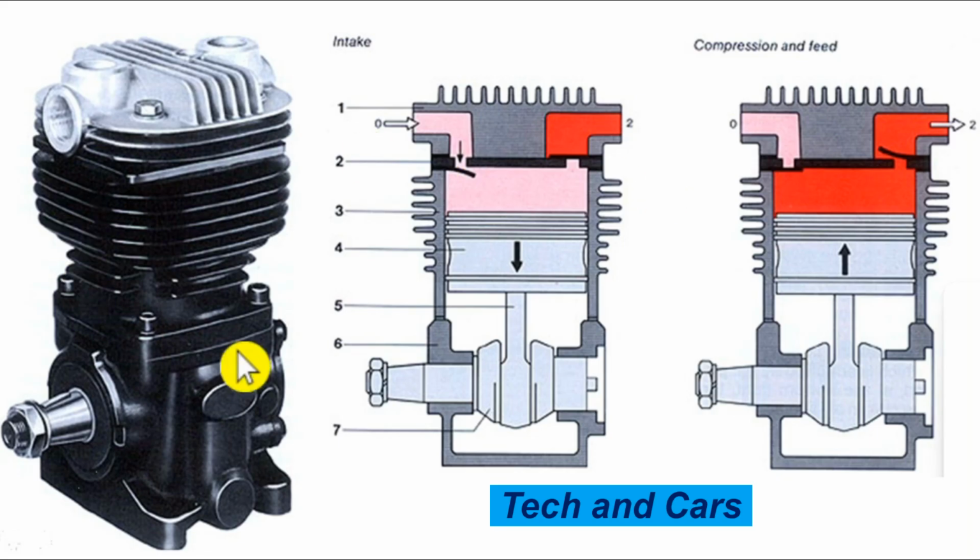So the golden rule for prolonging the service life of your air compressors: always drain the tanks every day. Make sure that the pneumatic system is moisture free, use the correct oil for your compressor, and always make sure that sufficient oil is available. Check the oil level regularly, and if there are any leaks, fix air leaks immediately, and service the air dryer annually. Listen for any unusual sound. If you hear a knocking sound or grinding noise, then address them immediately.